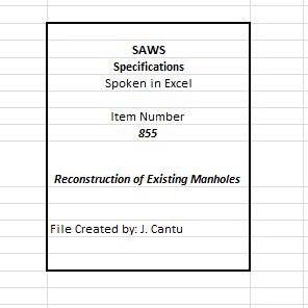C. Acceptance. Any manhole which fails the initial test must be repaired with a non-shrink grout or other suitable material based on the material of which the manhole is constructed. D. The manhole shall be retested as described above until a successful test is attained. E. After a successful test, the temporary plugs will be removed. F. To ensure that the plugs have been removed, contractor shall only do so in the presence of the inspector.